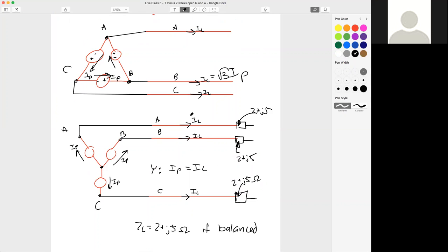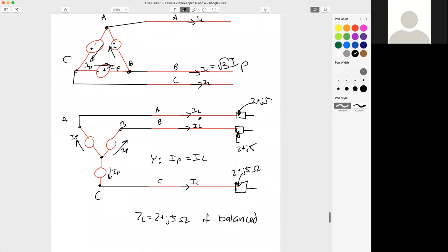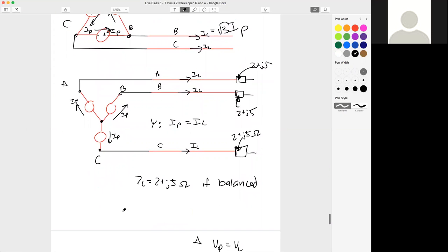So you never need to multiply the square root of 3 by your I, right? Now, let me preface that by saying some power formulas, right, is what? 3 times our single phase. So we would have 3 times our V magnitude and my I magnitude times what? Power factor. So yes, of course, you're going to see a 3 with an I from time to time, depending if you're working three-phase and single-phase formulas. But they're never going to say what's the total line current. You're never going to be expected to sum up the three line currents if you're just expressing amps.